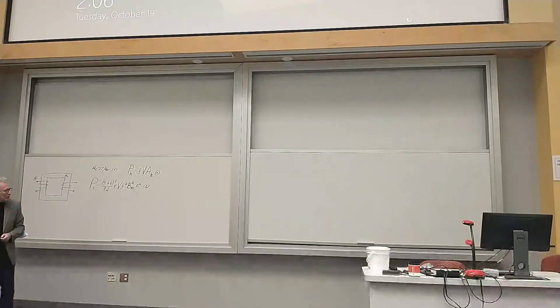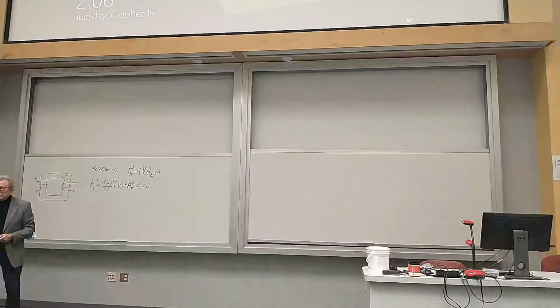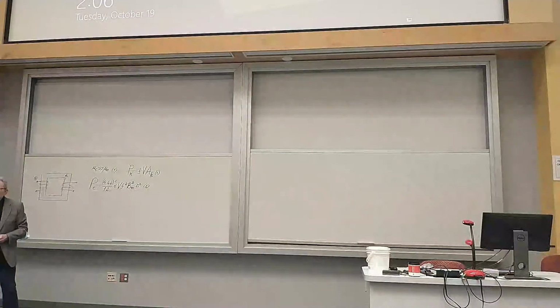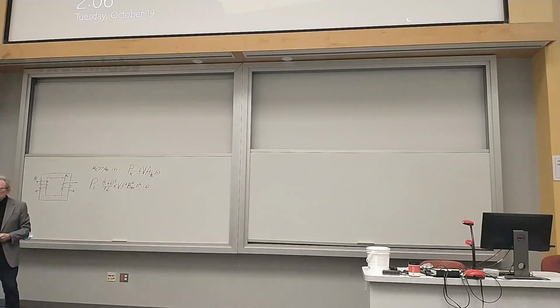In this way, we can reduce the eddy current losses by n squared times, where little n is the number of laminations. It has some negative effects as well, because it compromises the rigidity of the ferromagnetic cores, and it also results in some noise, which you usually observe when you stand next to transformers.